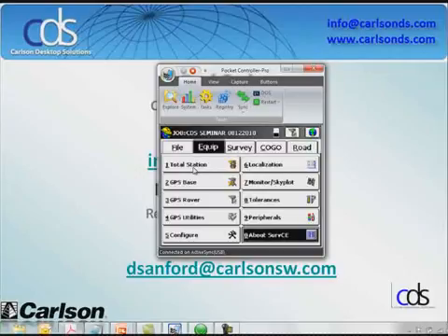Now, there are obviously two ways to work with the GPS, actually 3 ways. There's always a static type position, but the common 2 ways are either using a base and rover, typically using some kind of radio connection, spread spectrum radios, UHF radios, large 35 watt Pac Crest type radios, things like that, or using a single rover with a GSM connection to a reference network and going.